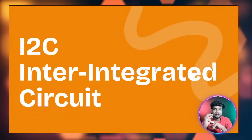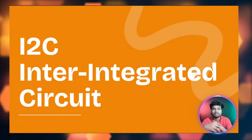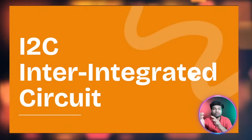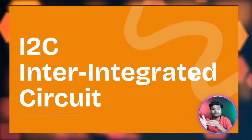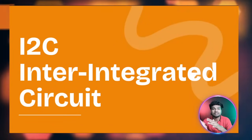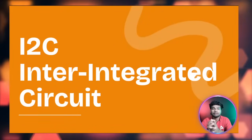So there is a race over who will firstly pull down the I2C data line. That particular master will win the arbitration, meaning that master will get access to the I2C bus, and then it will make communication between the master and the slave.